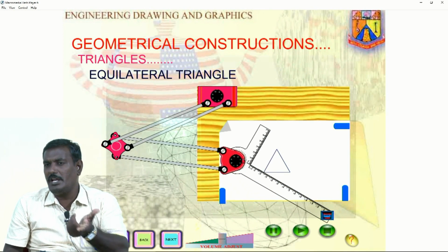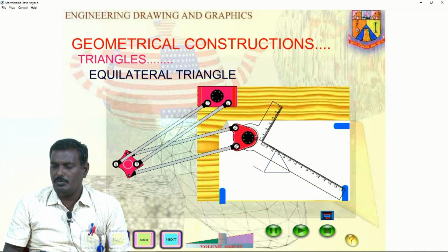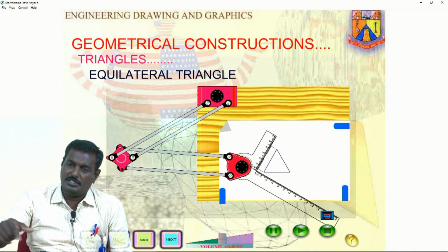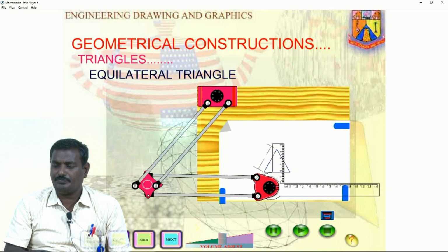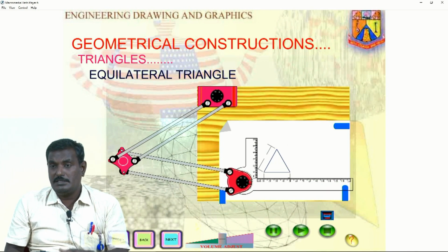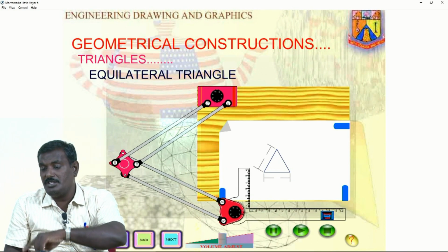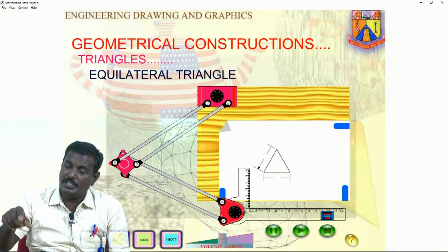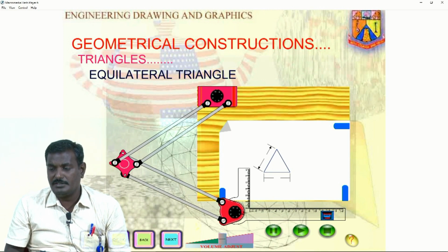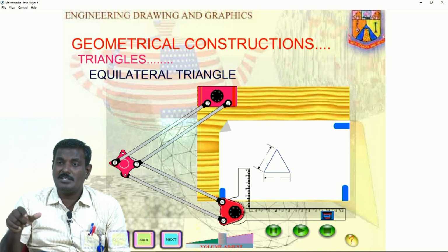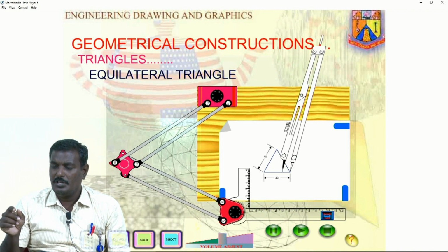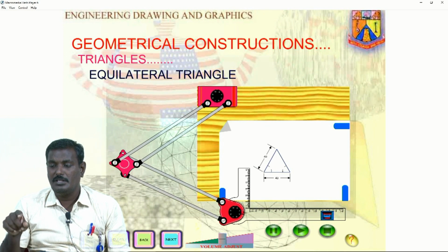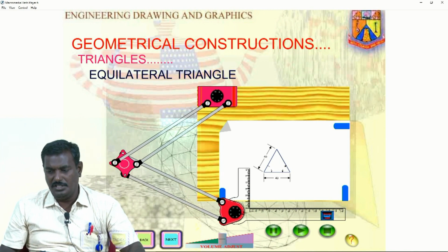Here I want to tell about included angle and excluded angle; later I will tell you about it. Try to look at the measurements and how to draw dimensions for this. Simultaneously I am telling about dimensions: horizontal dimensions and aligned dimensions. All sides are equal. After doing this text, then draw the angular dimensions. So what about the included angle? Here the included angle is 60 degrees.